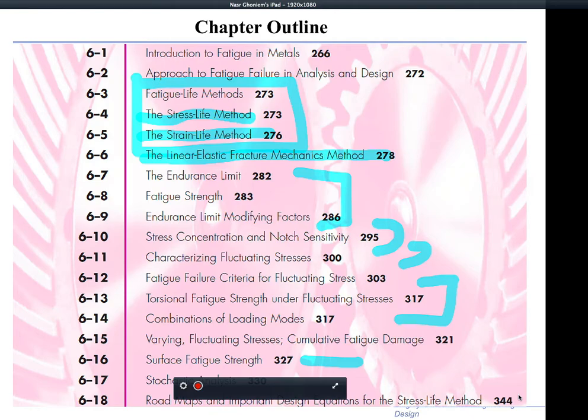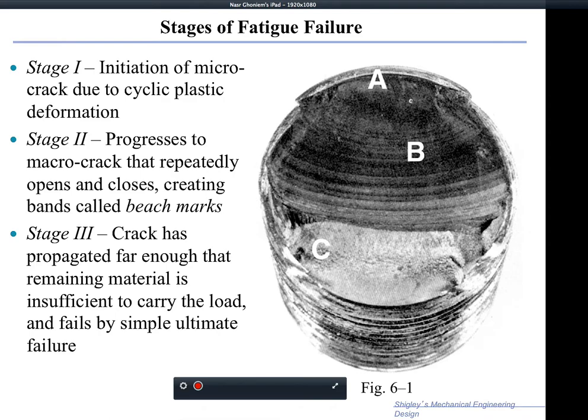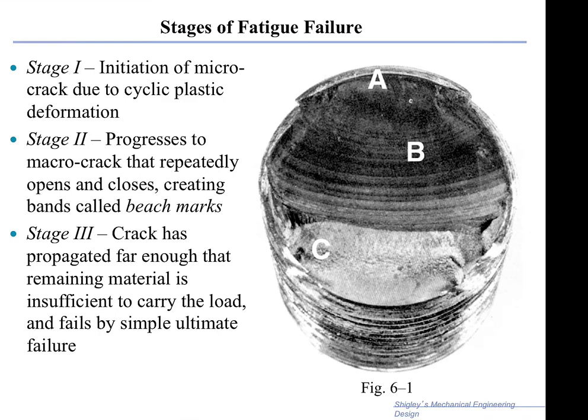So in here, what we have is an example that shows the different stages of fatigue failure. First, a crack is initiated at one location. So let's just say that we have a surface location where the crack is initiated, and then that takes a very, very long time, the initiation, maybe millions of cycles sometimes, to initiate a small crack.